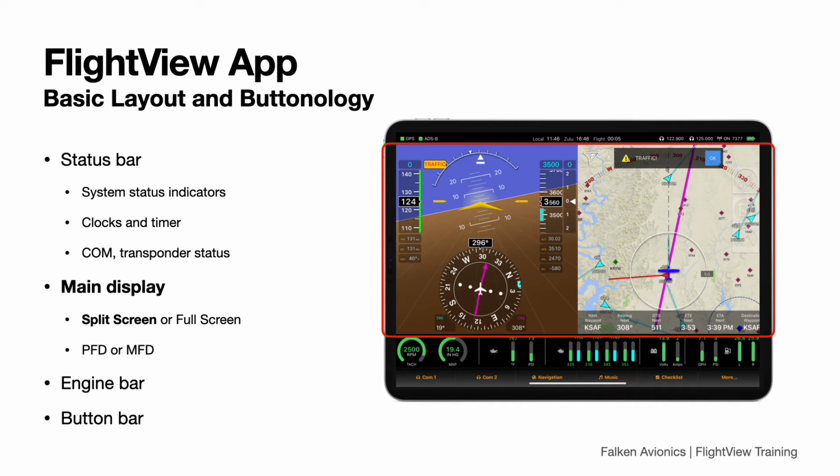Below the status bar is the main display section. This is where FlightView places most of the information used to operate the aircraft. This space can be configured as a split screen with the primary function, the screen that's most important, displayed on one side, and a secondary function displayed on the other. In this case, you see the main display section showing the PFD on the left and the MFD on the right. If the PFD is set as the primary function, the MFD will be replaced by other secondary functions, say the COM radio or transponder screens, when those are displayed.